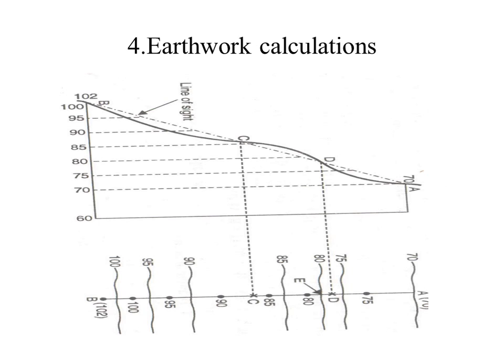Also, the contour map is used for earthwork volume calculation. Many times when we come across road construction or proposed road or railway construction, it is required to calculate the quantity of cutting and the quantity of filling, and that is possible by considering the formation level and the ground level at that particular location.